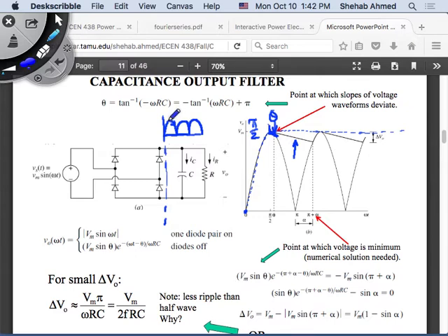Then, when this supply voltage tries to go down, it's trying to bring current out of the capacitor. Same logic we discussed last time. If it tries to bring current out of the capacitor, assume that this load does not exist for now. Then the current is going to try to go through these diodes, and the diodes will block, because all diodes here are pointing up. Current cannot go back. So diodes 1 and 2 will disconnect.